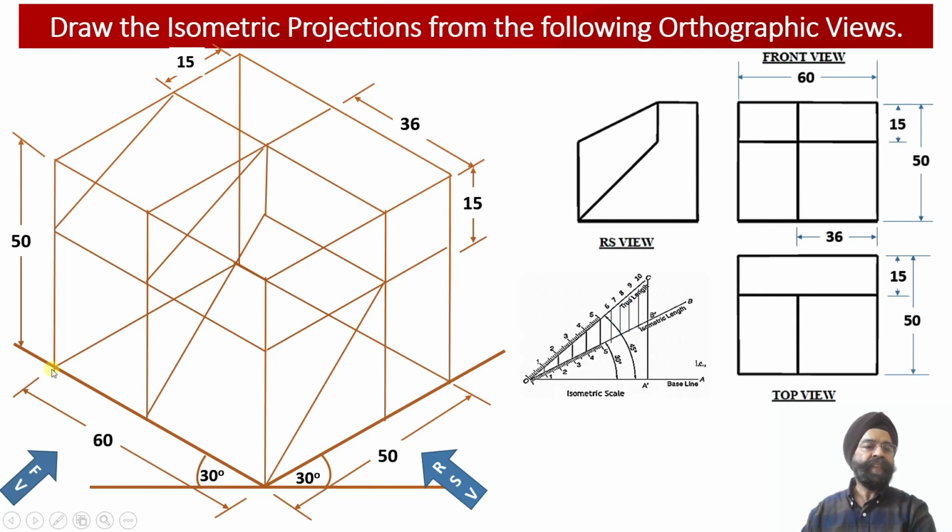So this way we are able to obtain the apparent shape projections corresponding to this inclined web into the front view projections, and the apparent shape projections corresponding to this inclined web into the top view projections over here. So this projection will be apparent shape. Similarly, corresponding to this inclined portion of this web, the top view projections will also be the apparent shape projections over here.